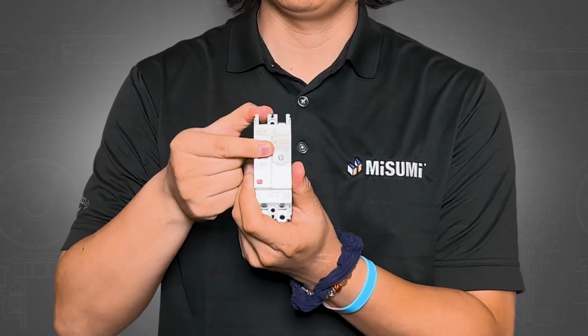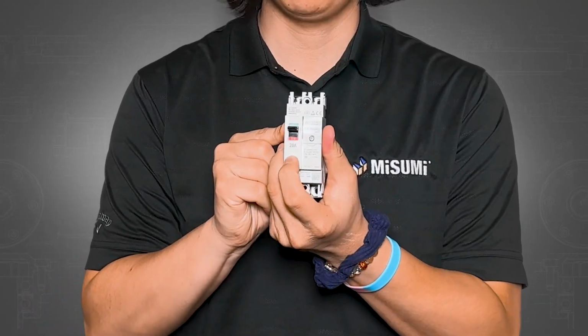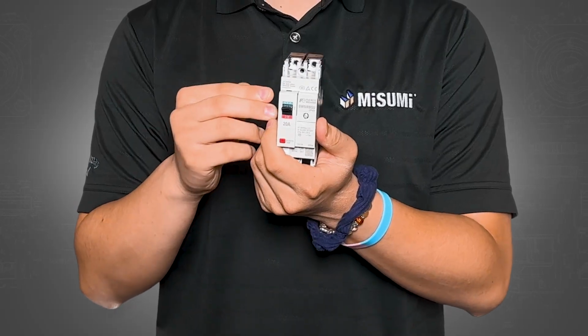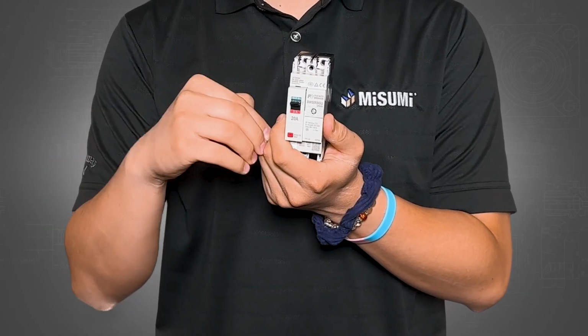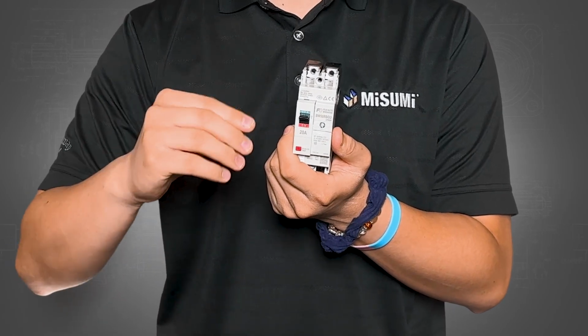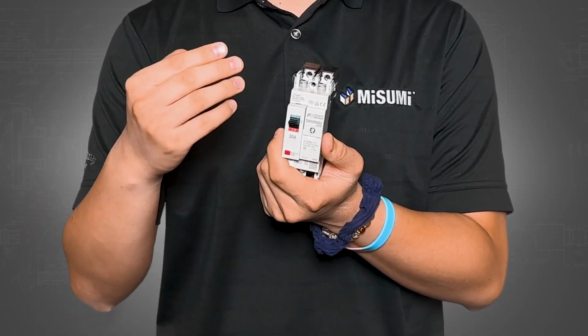The second one is the trip current, and that's the point at which the breaker goes from the on position to a tripped state, where it is broken, the internal connection is no longer allowing power to flow downstream. It's important to note that rated current and trip current are very different things. It is possible for breakers to experience an inrush current that is higher than the rated current, but not enough to actually trip the breaker. It is only when that inrush current meets or exceeds the trip current that the breaker will shut off.